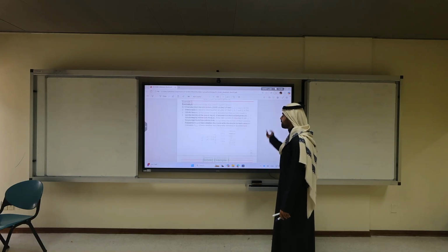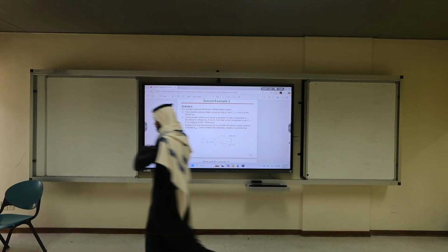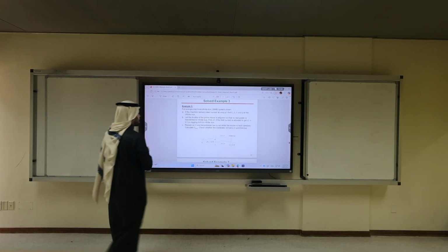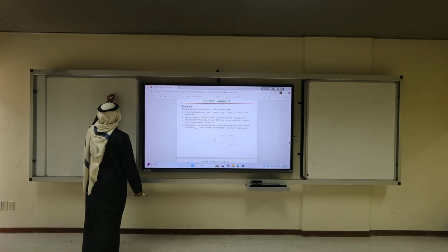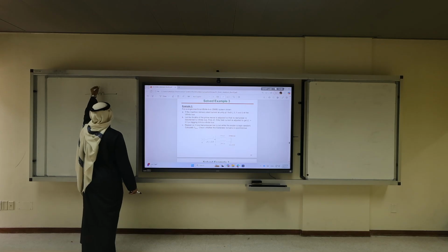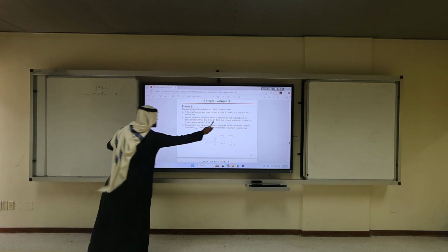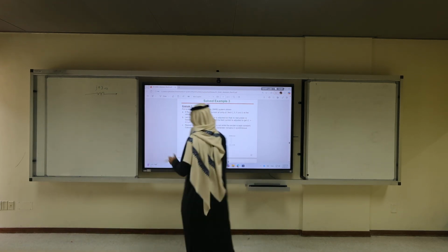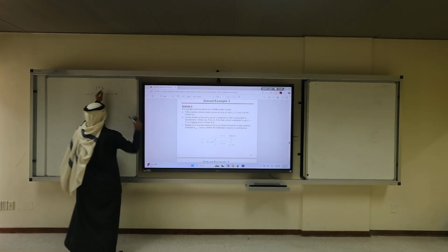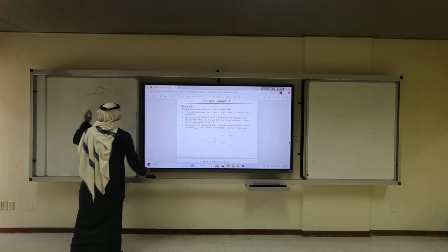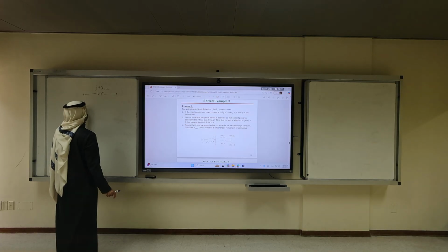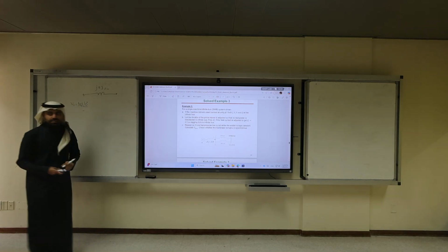So if we look at example 3 where you have the infinite bus, I'm going to draw that portion's single phase diagram with equivalent impedances. So what I'm going to have is j0.3 in parallel with 0.6 per unit. So it's not an ohm, it's in per unit of ohm, depending on ZB, we don't know what ZB is. And then here what do we have? We have V of t equal to a magnitude and an angle. We're taking it as a reference.